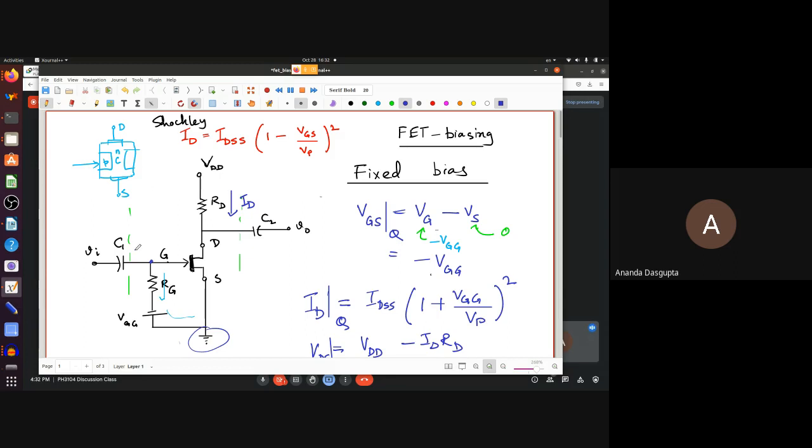Remember, there are two ways for which the source current can flow. Once it comes in here, it can go here or here. Very little current flows here. And if this resistance is large, very little current will flow here too. So the source will deliver very little current. And that's a good thing, because then the source resistance will not affect the output at all.